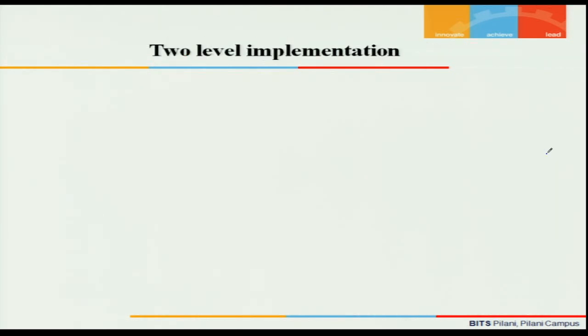We could now draw the circuit implementation for this product of max terms implementation. We will have the first level as a set of OR gates, because each one is a sum term. For this example, we had 4 sum terms, so we require 4 OR gates.